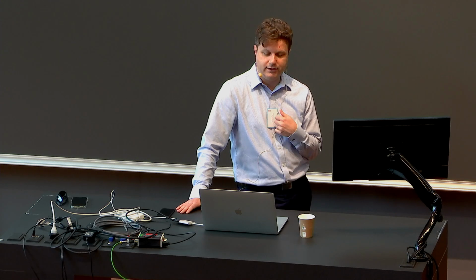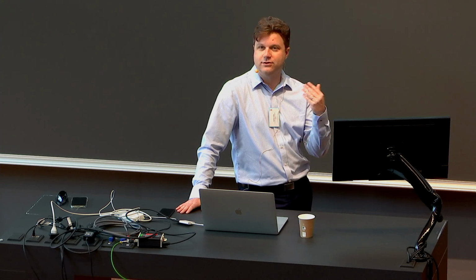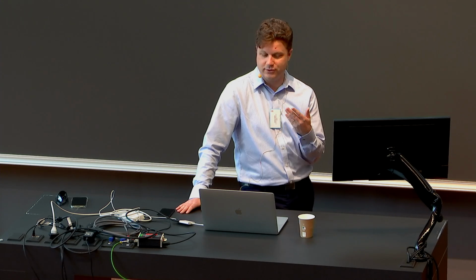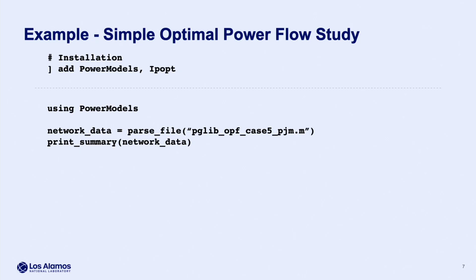The next step is that you need to load some data. So after you're done installing the package, you then can start loading it into your environment and using it. So the command using in Julia is how you pull a package into your current working environment. That will load some standard functions, like in this case, parse_file is a function that's defined by PowerModels for reading transmission network data sets. So if I do parse_file and then I give it a path to a data set on your computer, it will try to load it.